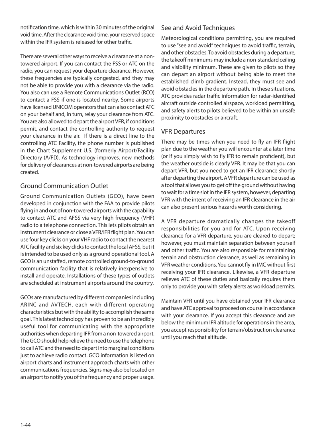VFR departures. There may be times when you need to fly an IFR flight plan due to the weather you will encounter at a later time, or if you simply wish to fly IFR to remain proficient, but the weather outside is clearly VFR. It may be that you can depart VFR, but you need to get an IFR clearance shortly after departing the airport. A VFR departure can be used as a tool that allows you to get off the ground without having to wait for a time slot in the IFR system. However,